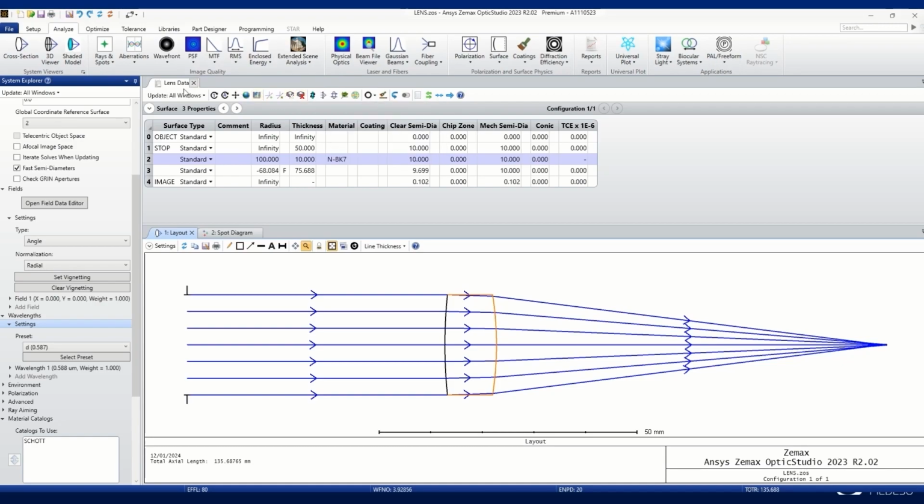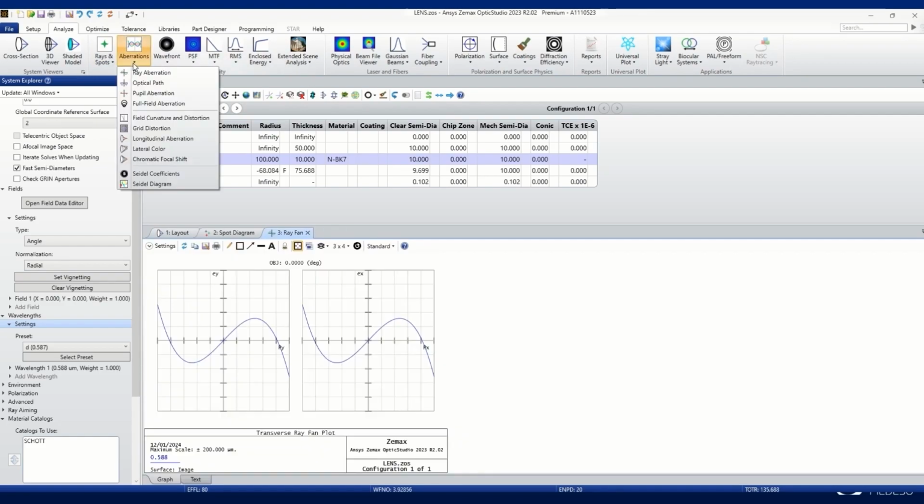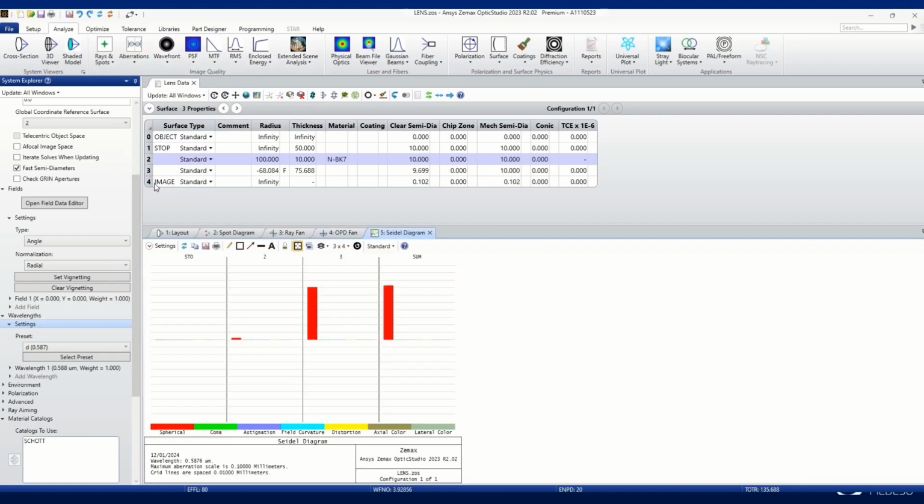of the optical design. So there's the ray plots. You can calculate the exact wavefront error with the OPD plot. There's a wavefront error here, and MTF. So there's a whole bunch of tools to help with this. I like to use the Seidel chart or Seidel diagram here, which shows the third order aberrations as you go through the system. So this analysis is fast, and it can be a nice way to kind of do inverse design as you work out where the biggest aberrations are coming from and how to remove or correct for them.